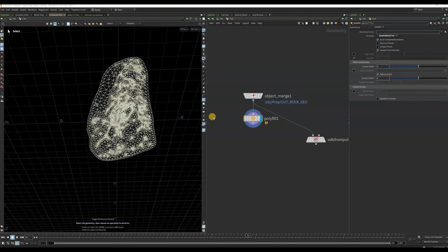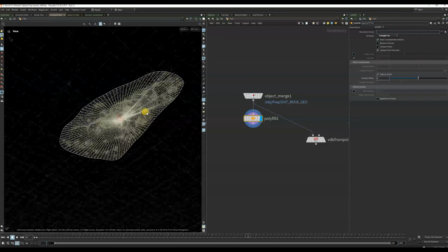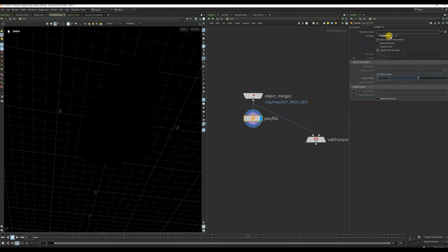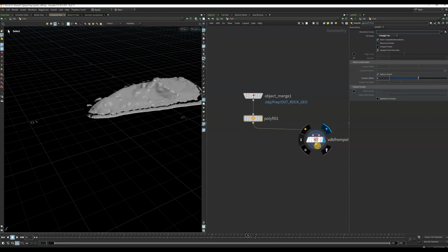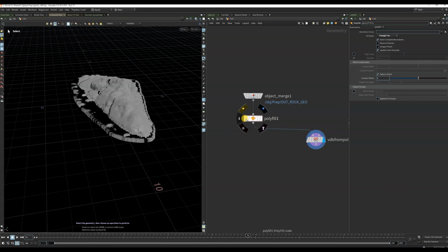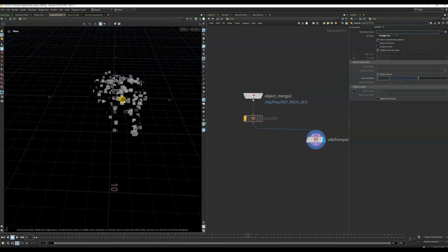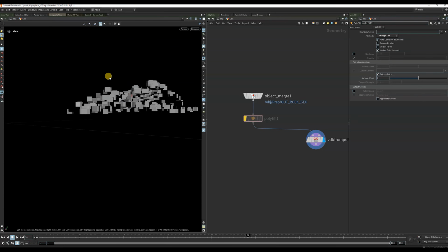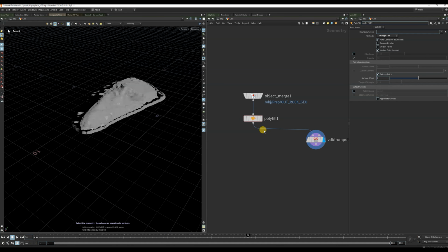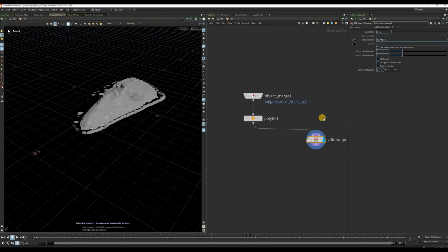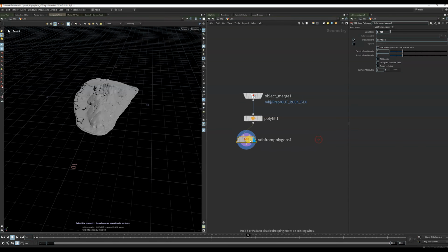Try this. Yeah, use this thing, triangle fan. Okay, and then I just use a convert VDB. Okay, so if you turn off this thing, this collision is broken because the inside of this geometry is empty, that's why. Okay, so after that you can get this collision, and here you can just increase the resolution. Okay, so you get a collision.